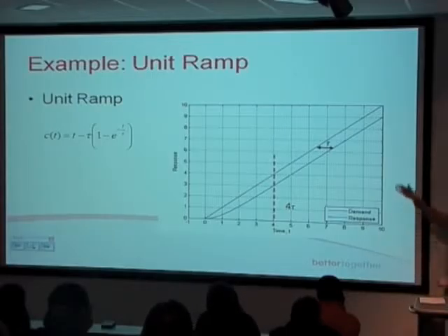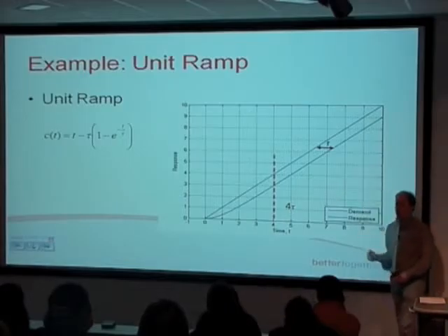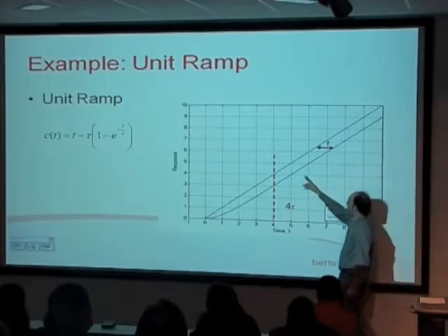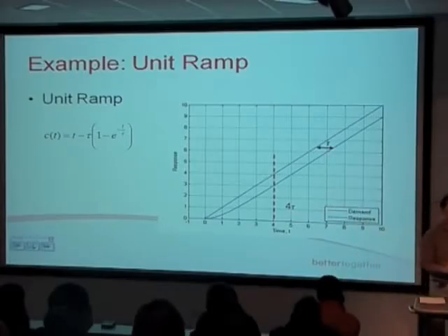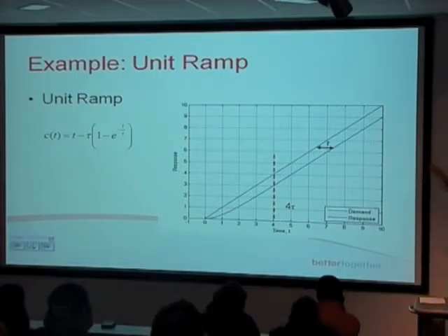And so with a ramp input, you'll always get this sort of shape, okay? You'll always have a lag of some degree. Obviously, the smaller your time constant, the closer you're going to be to what you demand. So as the demand increases, you get this lag, and that's denoted by your time constant. Again, showing why we put stuff in standard form, because if we know what tau is, we can automatically think about what the response is going to look like for a ramp input.